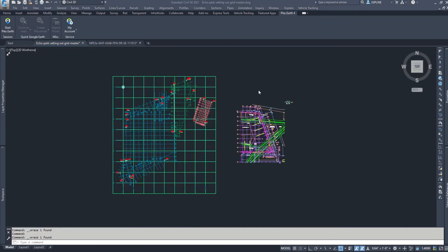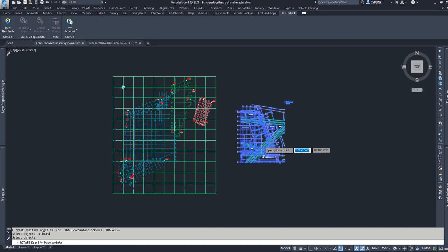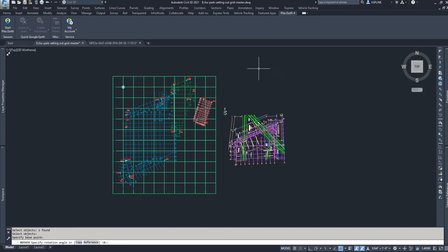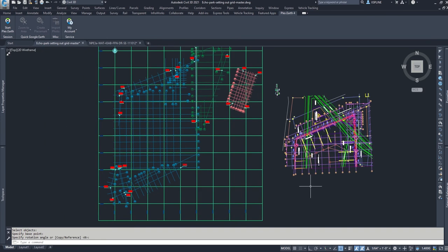Okay, so now we have the new model here and the reference file here, and we can see that this represents the top half of the building over here, but it's not rotated correctly. So get a rough rotation first of all. This needn't be accurate. We'll close in on accuracy when we do the alignment, but roughly speaking, it's around about 90 degrees that way. So you can see that matches roughly with what we have at the top here. Now we're better placed to find two coordinates.